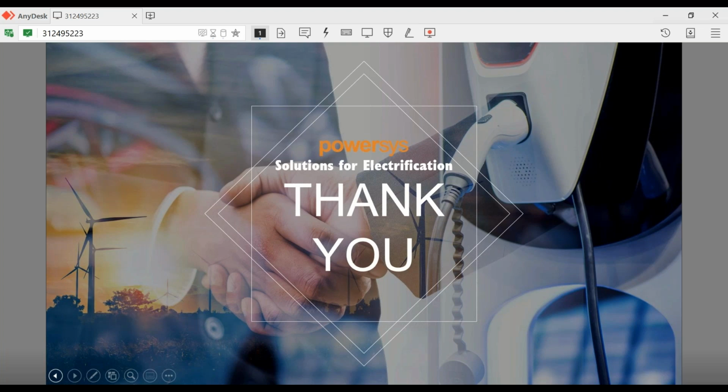The third-party software is the MPCCI interface. This is an interface completely dedicated to mappings between different software. And JMAG has the multi-purpose file export tool that allows you to map any quantities you have calculated in JMAG onto a third-party mesh.